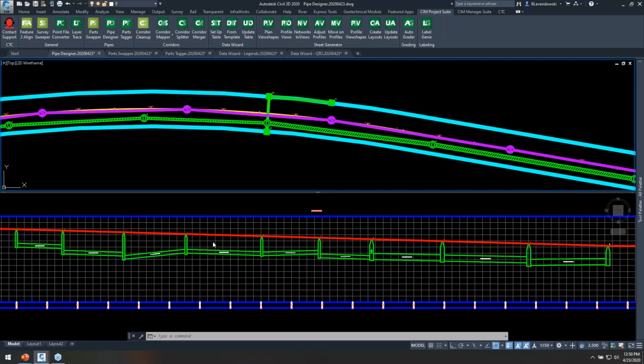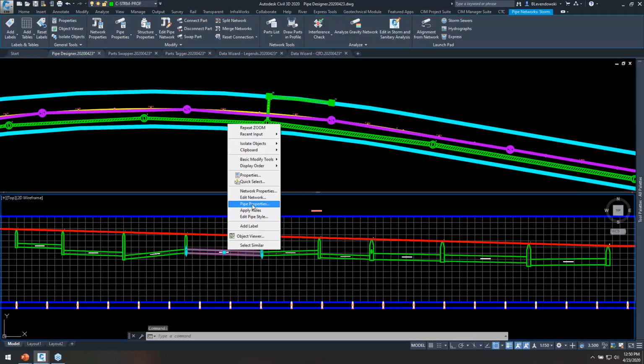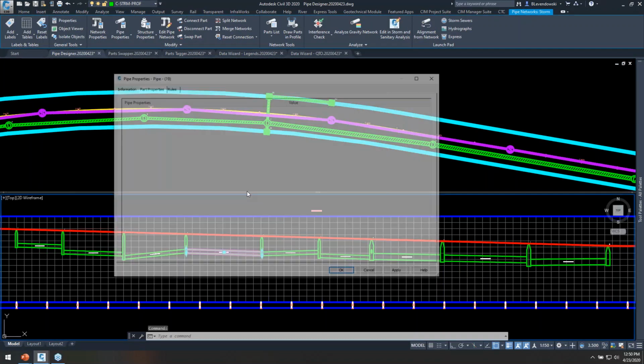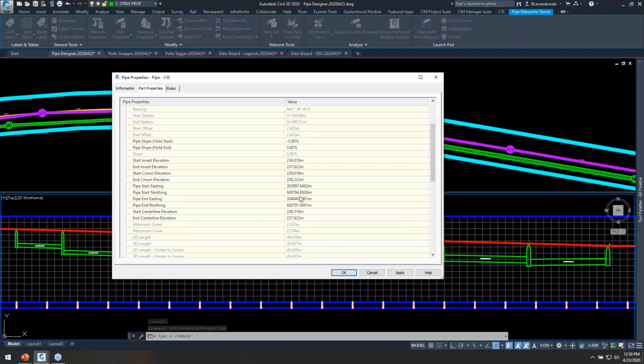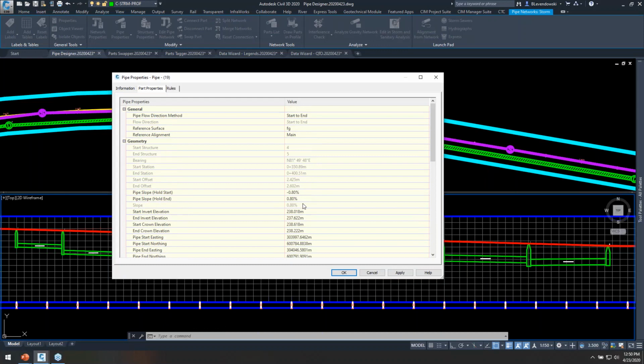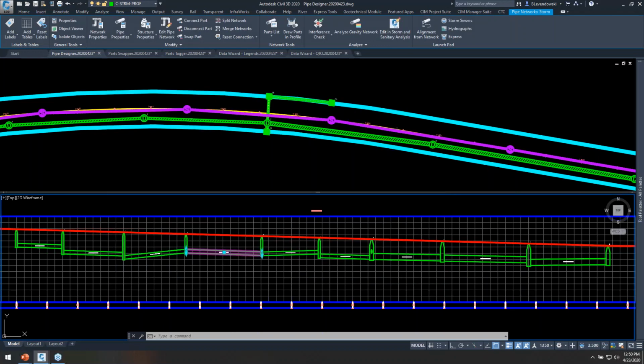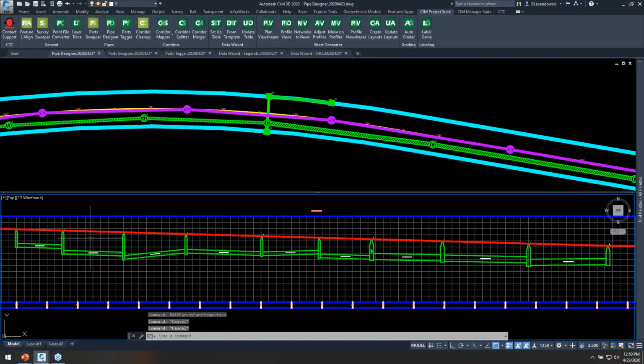Normally when you're changing slopes and inverts of your pipes, you have to come in and change slopes and inverts one part at a time. You can either do it in here, or you can do it in the Pipe Network Vista, but it's not really an interface that lends itself to how we think about gravity systems, storm and sanitary systems. I want to think in terms of